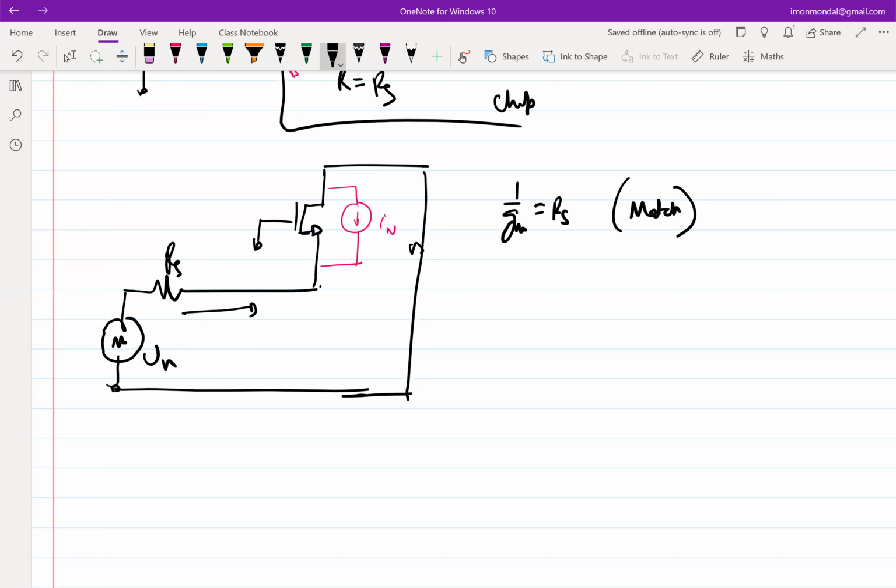a noise voltage equivalent Vn. So this current will be how much? Vn by 2 RS, right? Because it is matched, so impedance here has to be RS. So effectively, it's 2 RS. So Vn by 2 RS will be the current that flows into the short also.